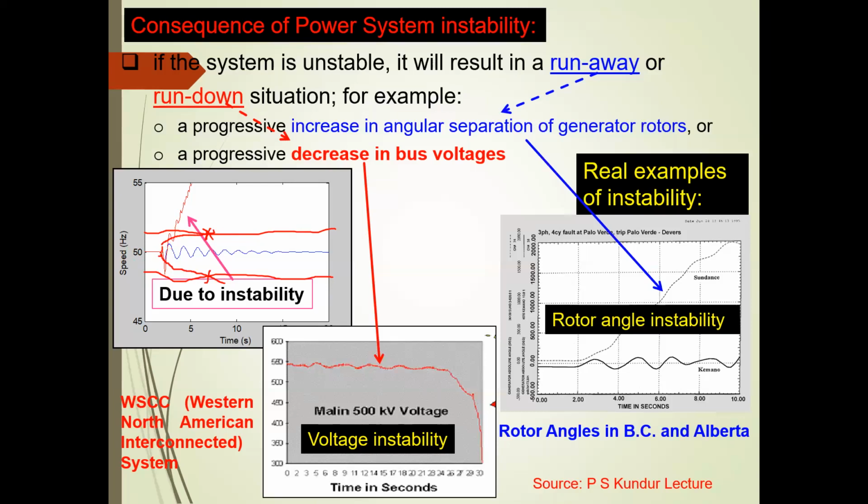If there is a sudden load disturbance, it is possible that the governor is not sufficiently able to regulate the output power from the generator, because the governor itself has a delay. In that case, the frequency can suddenly cross the upper limit, and then the relay will instantaneously trip.